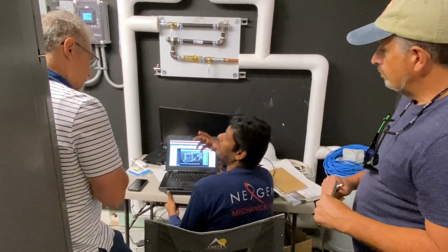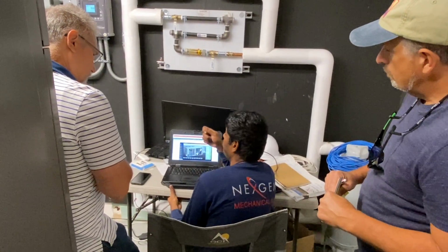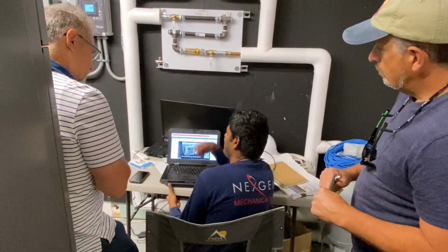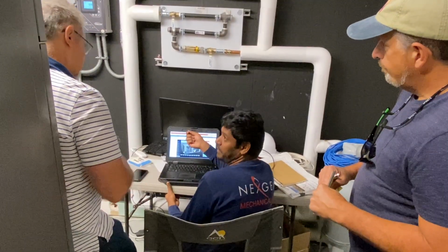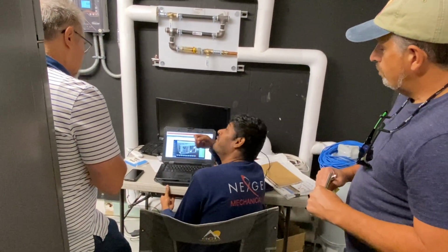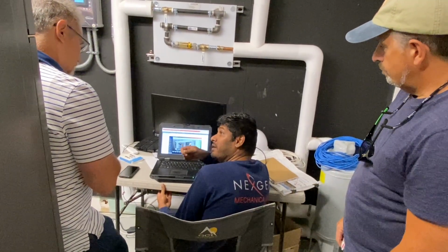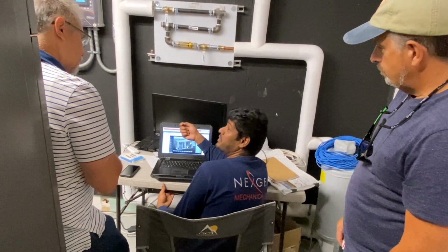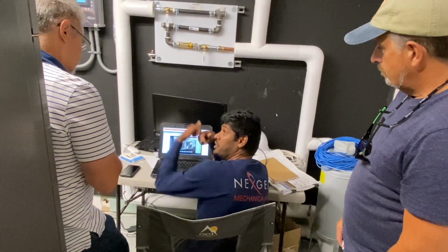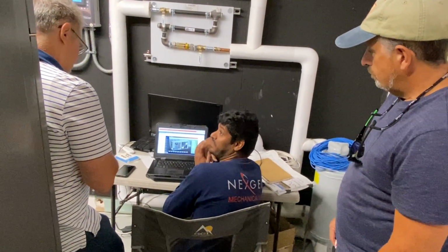With 20 VAVs, if only 3 are overheating, it's not going to affect my space temperature, so I'm not going to bring in my cool down mode. If 6 to 7 VAVs are overheating, then by math it's going to affect my average space temperature. Then I'm going to bring in my cool down mode if necessary.